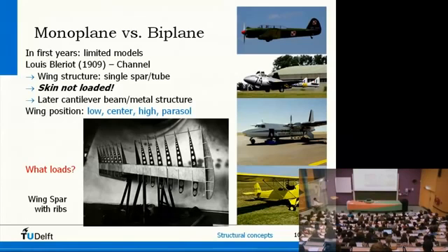What kind of loads can such a tube take? Think about bending or torsion or tension or compression. Can I put a tension load to it? Compression? Bending? Torsion? So such a tube, such a box is actually quite sufficient for a lot of loads. Later on, when we are a number of slides further, you will see that most of the wing structures have in the center some kind of wing box, some closed area where we also put in the fuel. But that's not only to put in the fuel, it's also for taking up a lot of loads.